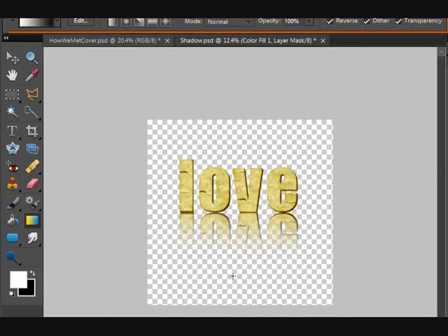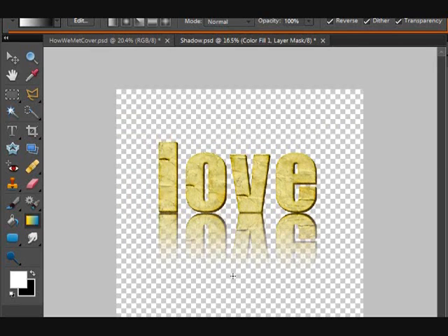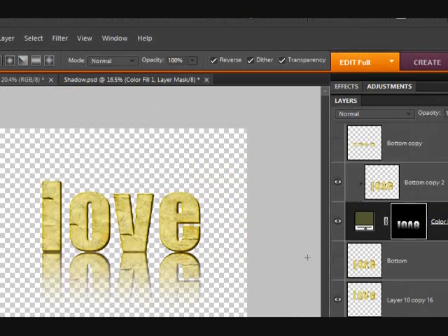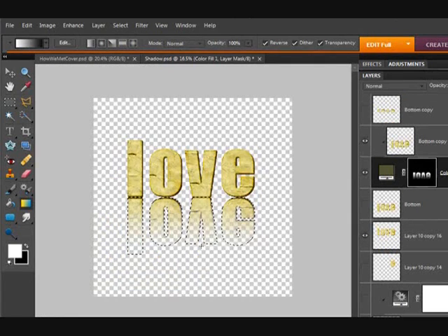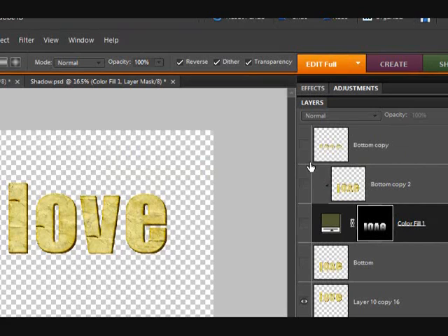But that is how you do it the non-destructive way, because as you saw, I just went back and redid it. See, I didn't hold down my shift key, so this G is showing a little bit too much. So I'm going to make that selection again, make sure I'm on my mask, hold down my shift key, and do this one more time. Control D. So that's why it's non-destructive. I can keep going back and playing with that and changing how that looks if I want. But let's hide these and move on to the next step for now, using the destructive way.